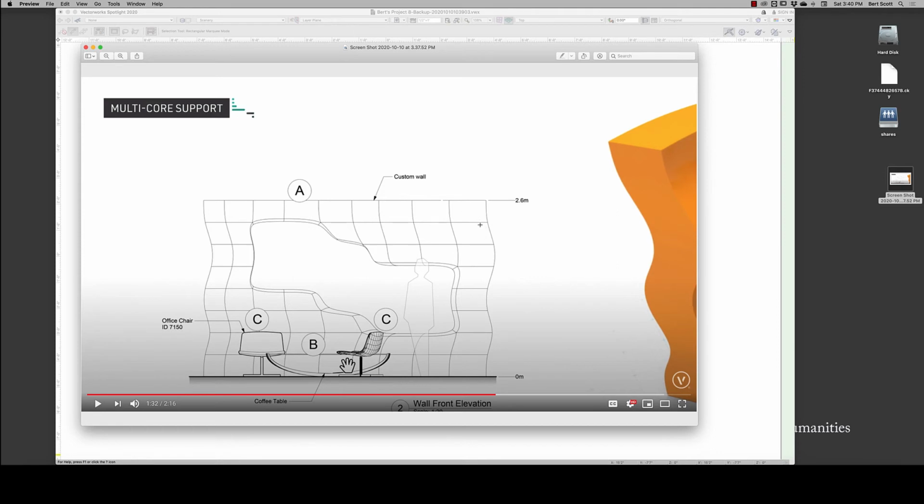That would either give me just the outline of the wall, or if I change the settings, it would show me all of the little subdivisions, the thousands of them in the final smoothed version. So finally, while trying to do something else, I happened upon converting this into NURBS, which seemed to break it up into these divisions.